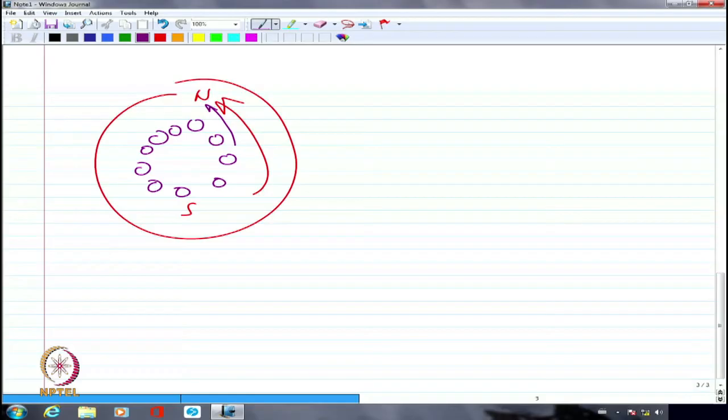It will stop because you are not going to have any more induced EMF, any more induced current, any more rotor flux. All that completely disappears. If it disappears, there is no torque. If there is no torque, the rotation will automatically try to come down. The velocity will come down. The moment the speed comes down from the synchronous speed, again you have induced EMF, currents and torque and everything.